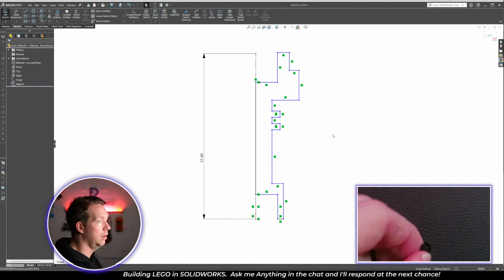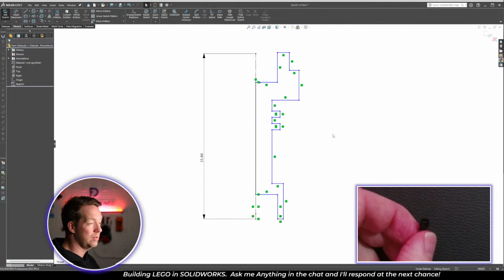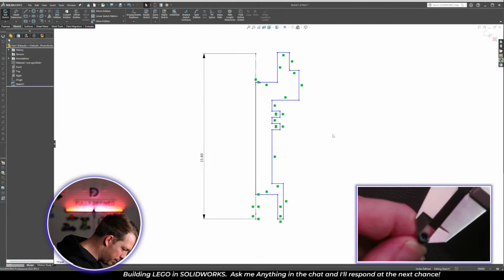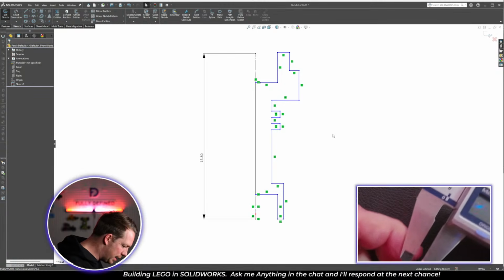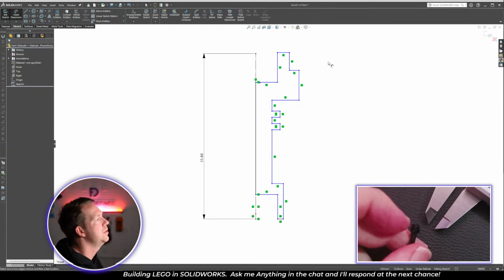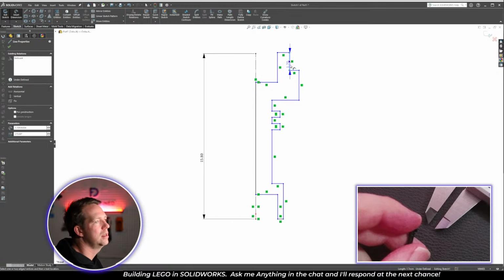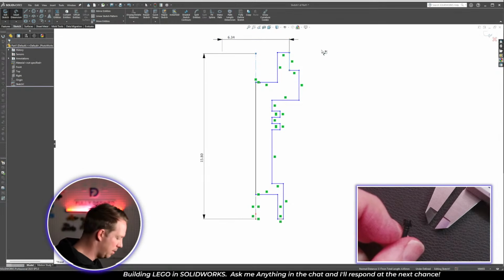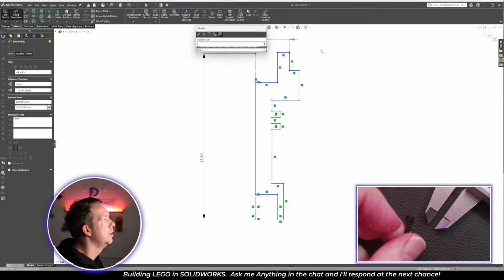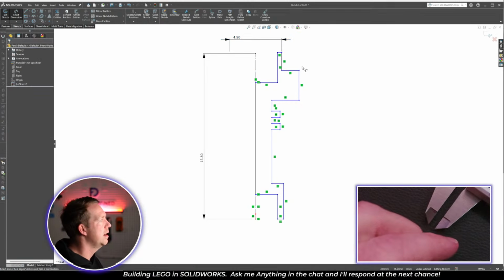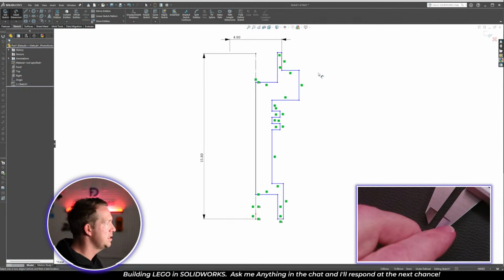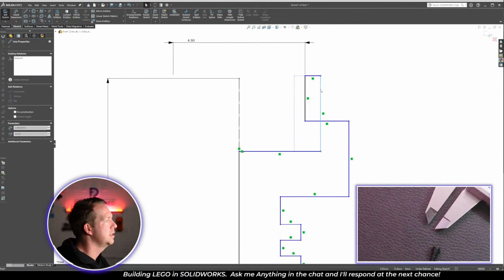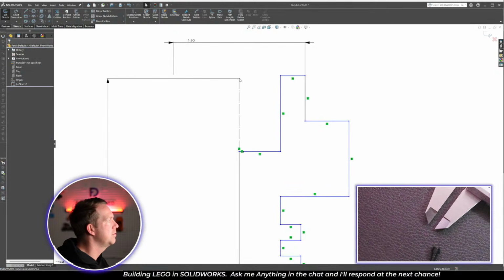All right, so now some dimensions. So we've got our sketch in place. Now we're going to measure some of these elements. So outside to outside, when we're doing this, I can select the outside, select the construction line, roll over, and then put in my dimension. And that's going to give me like a diameter. Now, it might stuff up some of the sizing. Okay, you might find it goes like this, that's fine. Just adjust your sketch afterwards.